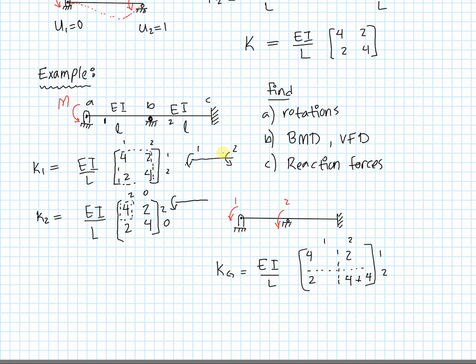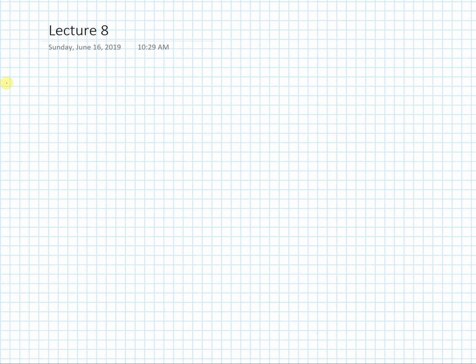Okay, so the next thing I want to do is to ensure that I've done everything correctly, which appears that I have. And what I need to do is to really wrap up this matrix, and I should have a matrix that looks like 4, 2, 2, and 8. Okay, perfect. All right, now I want to apply my forces, invert my matrices, and obtain my deformations. So I got K global times the deformation is equal to the forces.